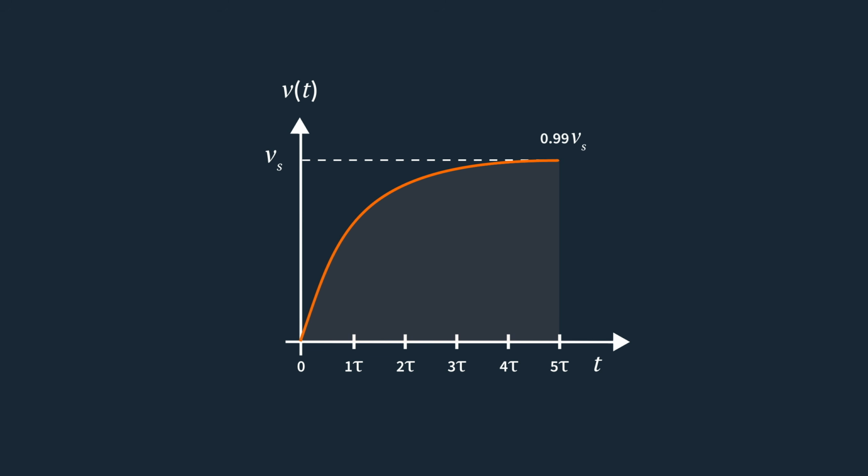I've been focusing on RC circuits because they're slightly more common than RL circuits, but RL circuits with the resistor-inductor relationship behave the same way. However, instead of voltage changing exponentially, we typically watch the current change exponentially. Swap out voltage for current, and the math and concepts are basically interchangeable.